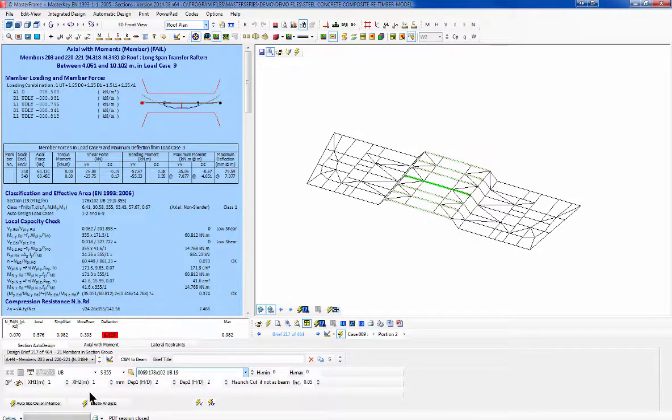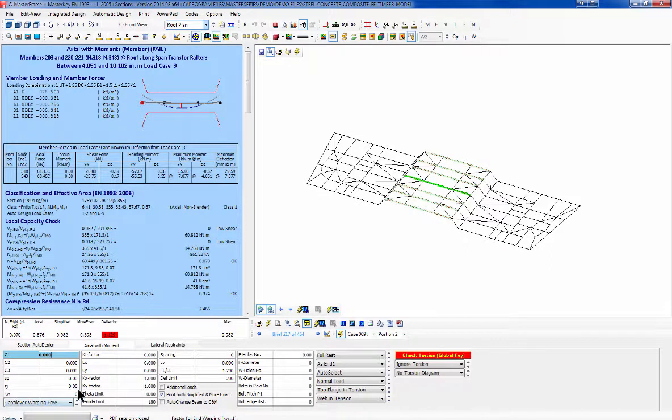Now you could turn around and say, well, actually somebody's already set the deflection limit down to 200, so it's already relaxed that deflection limit down to 200 from 1/360 because it's a roof member. So I'm not going to mess around with that. I'm going to accept that.